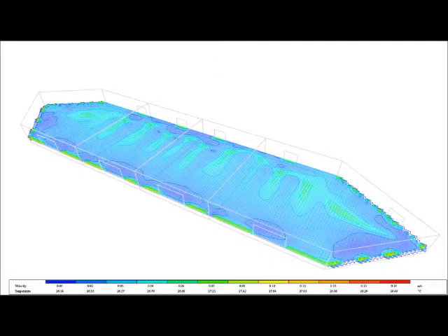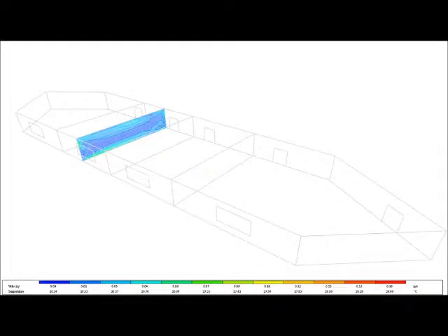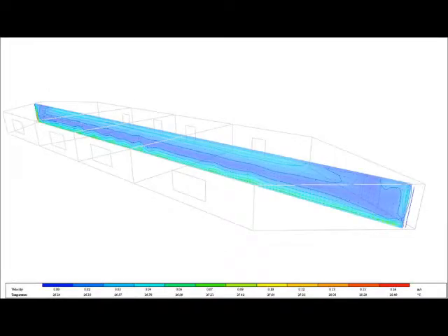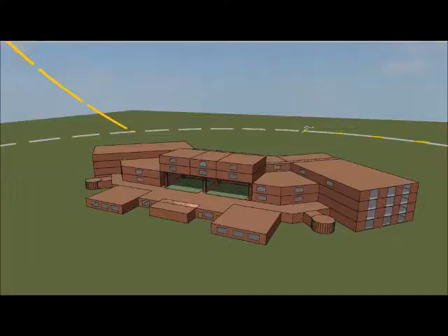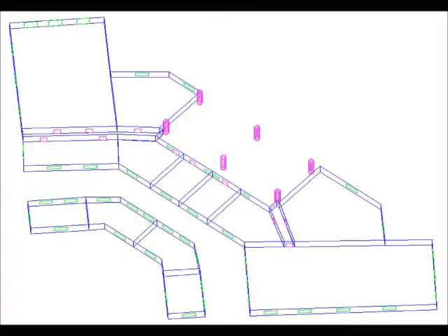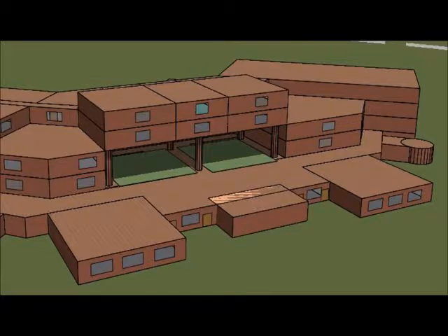to trace changes. The indoor temperature at the base case is recorded at 26.7 degrees Celsius and wind velocity at 0.04 meter per second. The cross sections are showing a poor velocity across the room. In order to create a courtyard while keeping the built-up area fixed, we moved the designated area 2 floors up, as shown in the 3D, and created a shaded courtyard at the 3rd floor and added a green surface where it can be utilized as an outdoor refreshing area linked to the clinic rooms.